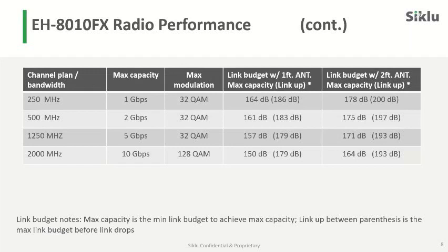What the dual-step transmit power control will do, as soon as the rain event is detected, basically as soon as the remote end reports that the received signal is degraded, is boost up the transmit power on the near side, which will translate into an improved signal on the far end and the ability to maintain the highest modulation and highest capacity most of the time.